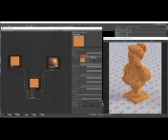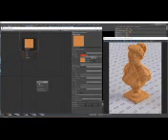now I can increase the scale to something like 200 centimeters, and get a much bigger map projected onto the geometry. Or I can rotate it on X for like 50 degrees. So you have all of these controls. The next important map is UVW randomizer.